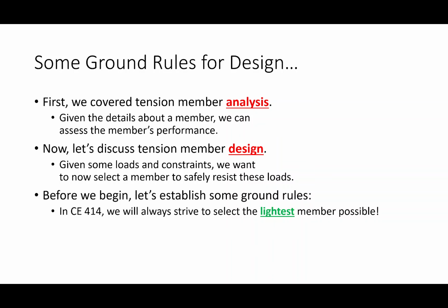How many floor beams do you think are in this building? Quite a lot, right? There's hundreds of floor beams in this building. And so maybe designing each beam individually would result in hundreds of different designs that would make the contractor's life a nightmare. Instead, we'll pick a restricted number of sections and just repeat them throughout the building.